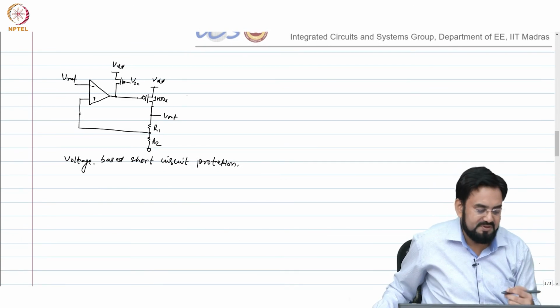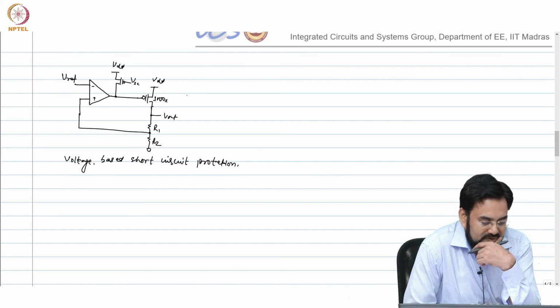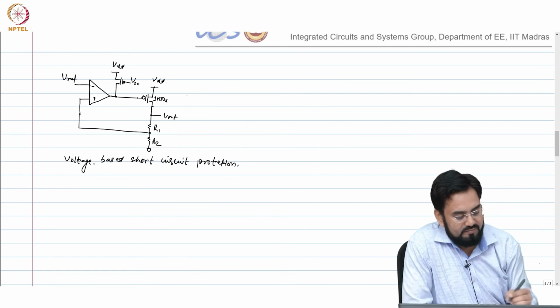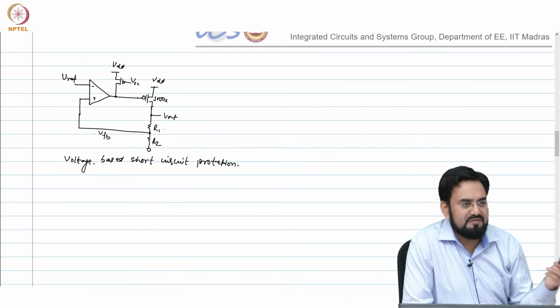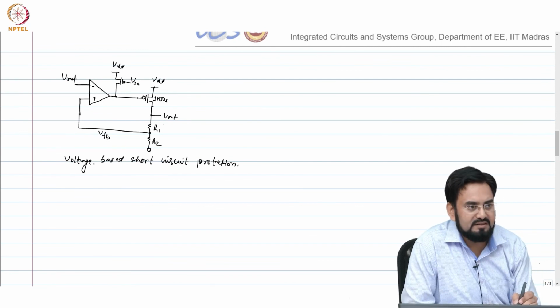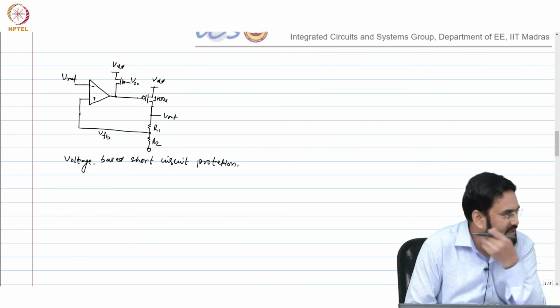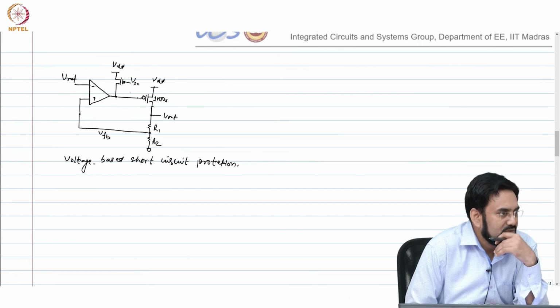If I want to generate the same control voltage to turn off your PMOS power FET, which voltage needs to be sensed? Output or feedback? Because when you start drawing high current, this will go out of regulation because your MOSFET cannot carry that much current. So your output will start going low.